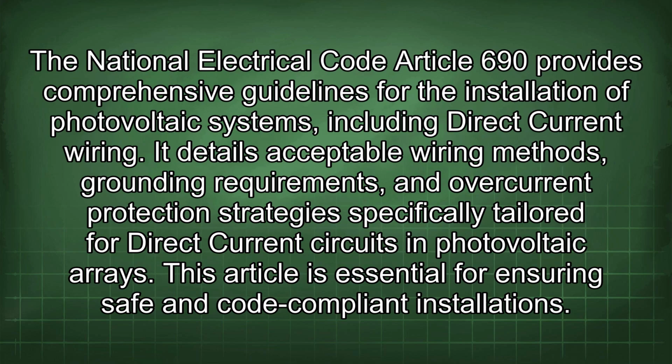The National Electrical Code Article 690 provides comprehensive guidelines for the installation of photovoltaic systems, including direct current wiring. It details acceptable wiring methods, grounding requirements, and overcurrent protection strategies specifically tailored for direct current circuits and photovoltaic arrays. This article is essential for ensuring safe and code-compliant installations.